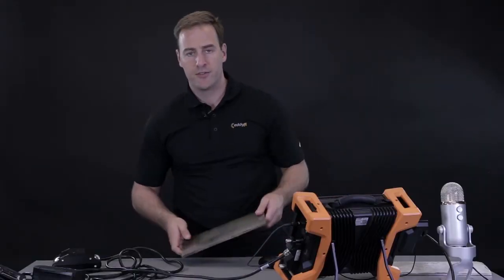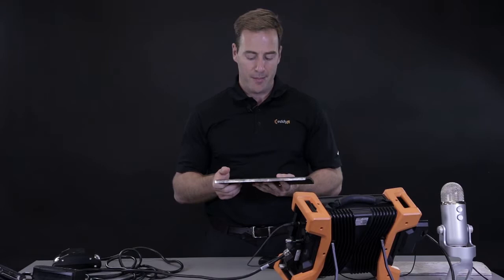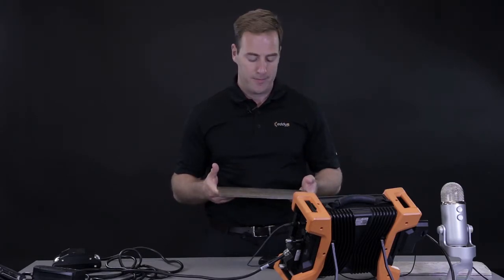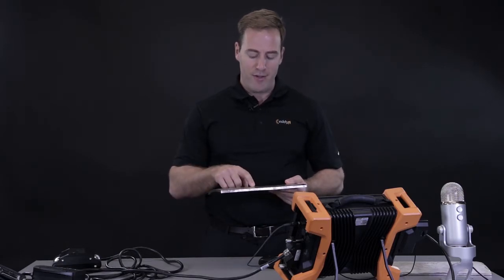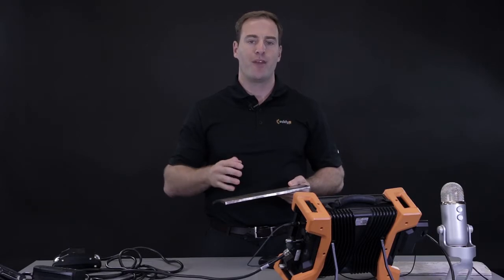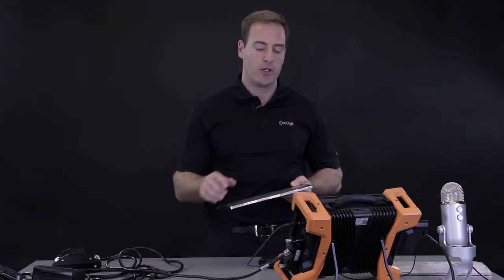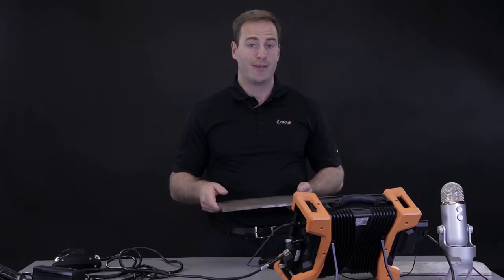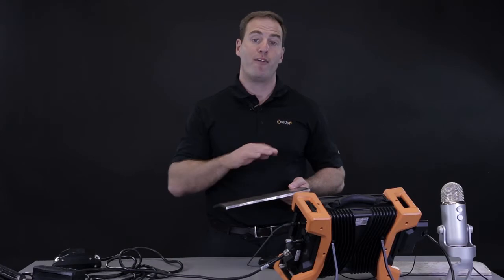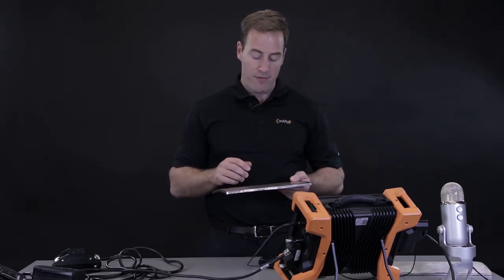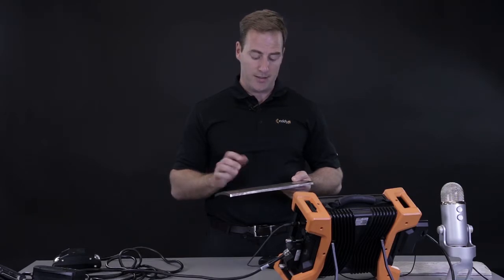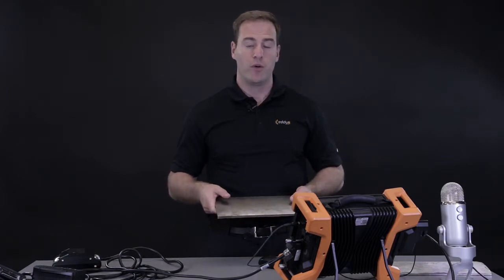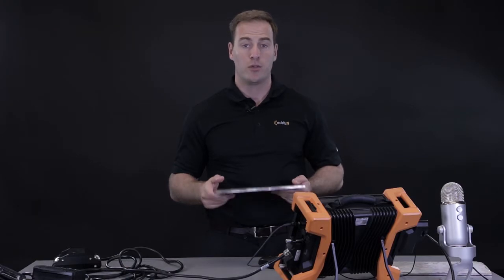On this plate here, this is an X52 sample, and we added some EDM notches in it with various parameters in a way to simulate some features that we could meet on real SCC. One of these defects has a bottom with different depths at 1, 2, and 3 millimeter. As I'm going to show you, we're going to be able to detect size and also track the profile of these cracks. We added also some very short cracks to show the high sensitivity of the probe, and also some cracks side by side to evaluate the transverse and the axial resolution of the probe.